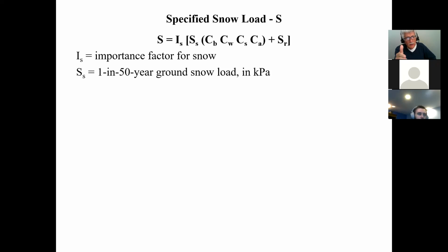They can be back to back, in other words, 1 year after the other, but when they accumulated the data, they found that the one they use within a 50-year period was the maximum value, and that's how they came up with that 1 in 50. So this is just the probability of it happening once every 50 years, the value that they put here.